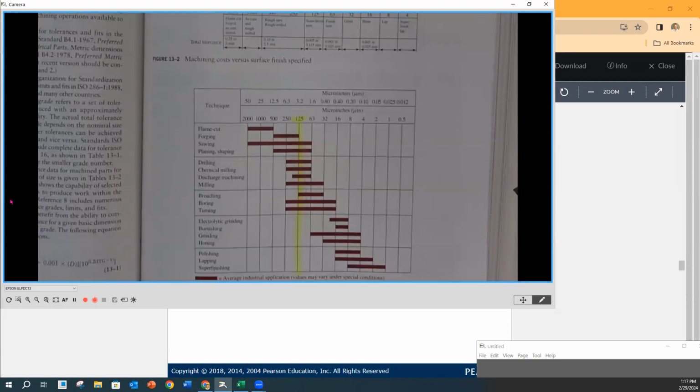Okay, all right. And even there, BJ, just so you know, when you're expecting something to be machined, it's not expected anymore to put a finish mark on every single feature. When it's obvious that it's a 3-place decimal and you're going to be milling it, unless you want it better than that, you wouldn't put the finish mark on. Or let's say you're just cutting something off and maybe the length isn't functional, but you don't want a rough saw cut on the end. Even though it might be okay to deviate plus or minus 20 thousandths, I just want a nice little cleanup on there, 125, so it looks nice.